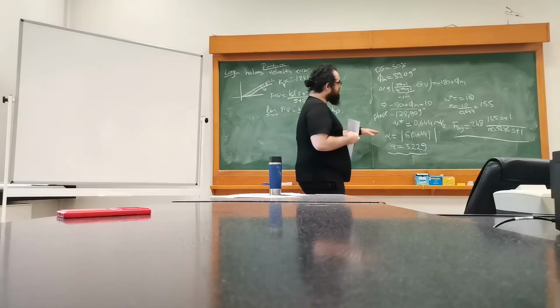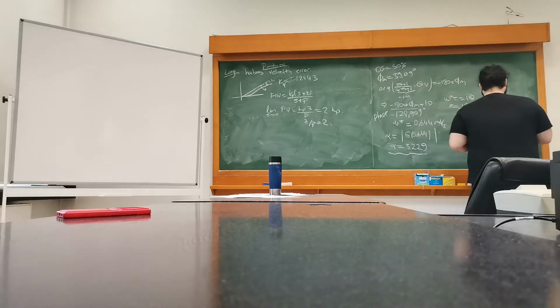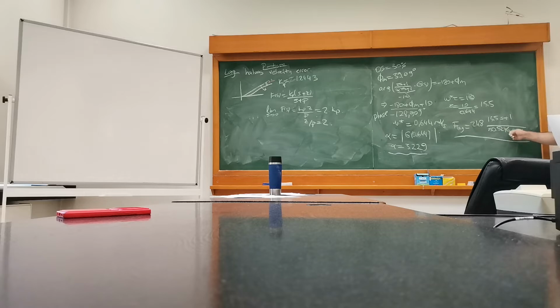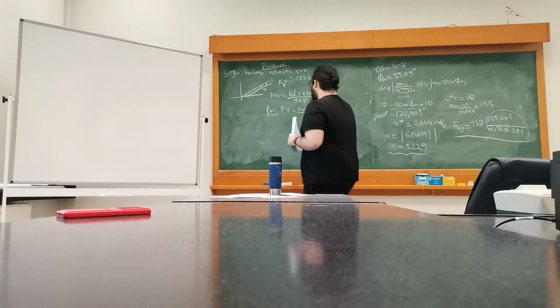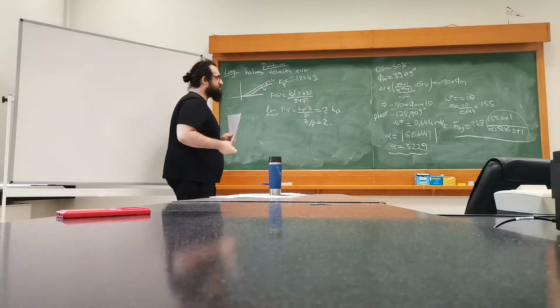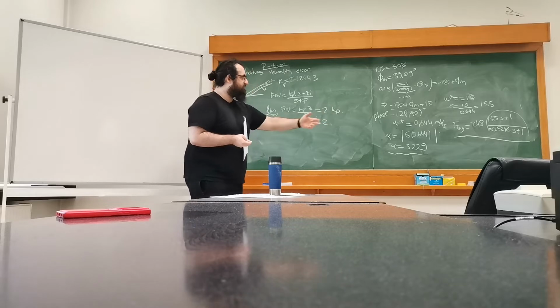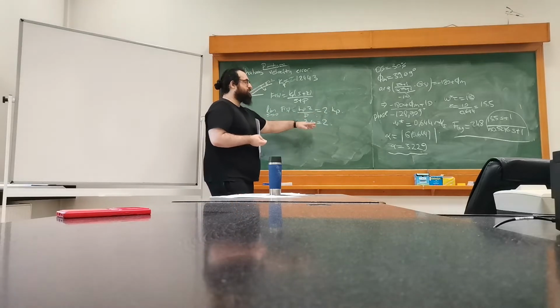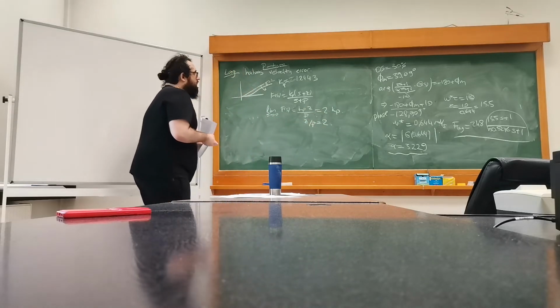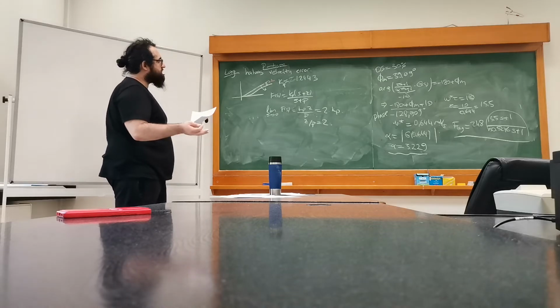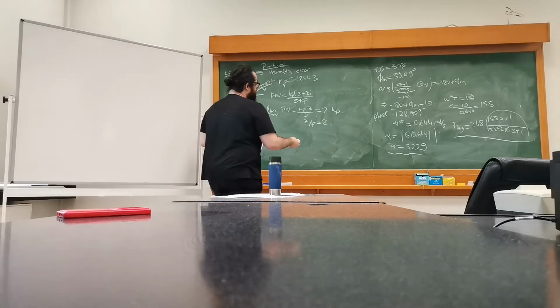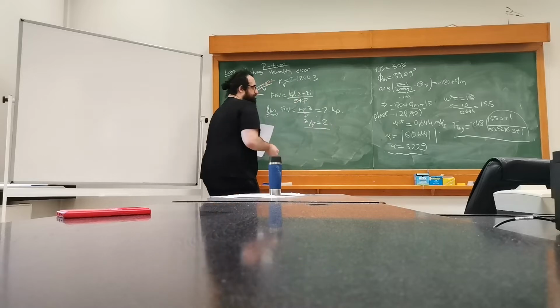Now, note that we are using alpha and tau. So here, if you plug in s equals 0, you have gain 1. So the DC gain of this whole thing is equal to 1. Therefore, you will have 2.48. So that doesn't really change. Here, we want to affect with the position or the location of the zero and the pole, such that we have the corresponding 2.48 value. Therefore, I'm leaving that to the z-p ratio here. And that's basically it here. We have the only information that z to p should be equal to 2.